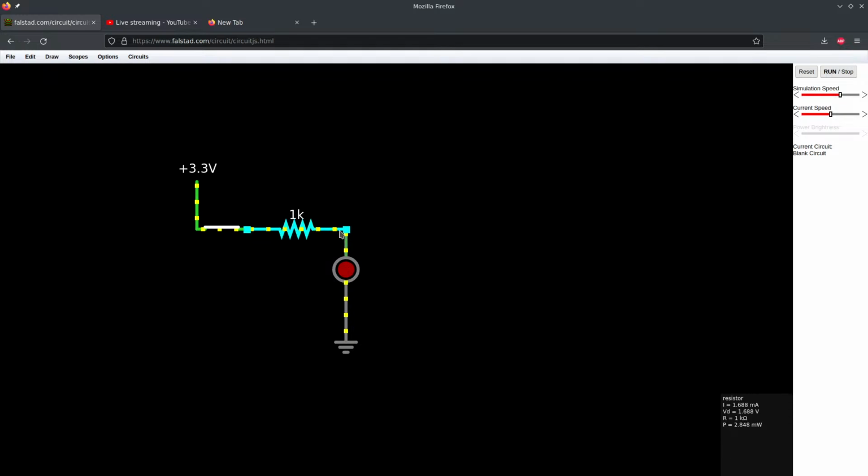We have to have a resistor in here because the LED, once you've gone over the voltage it needs, conducts way too much current and would potentially damage your microcontroller. So if I take this resistor out and just make this a wire and connect it straight to the LED, the simulation is saying we're putting 18 amps through it, which is way, way too much. These are usually 10 milliamps, or 5 milliamps for small surface mount ones.